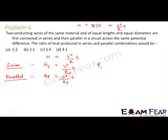Now let us try to calculate the value of Rs, that is the equivalent resistance in series combination. This will be equal to R plus R, because resistance of both the wires will be same. They are made up of same material, they have equal lengths and they have equal diameters, and resistance is given by rho L by A. So rho will be same, L will be same, and area will also be the same, therefore the resistance of both the wires will be same. So let us assume that the resistance of each wire is R. So equivalent resistance in series combination will be equal to 2R.